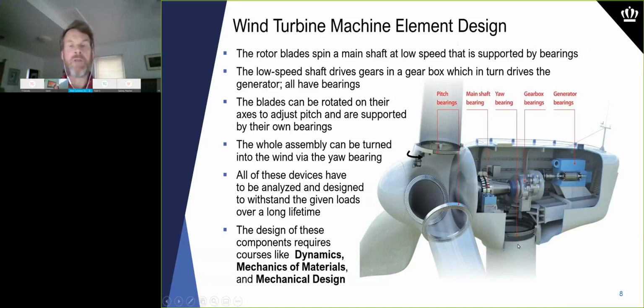We're going to rotate that on a bearing that sits on top of the streamlined pole. So we're going to point the turbine into the wind direction. And the problem is that the wind is actually varying, right? The direction's not exactly fixed. So we're going to use some sophisticated algorithms to look at the wind data, to average it over a period of time and say, okay, the mean wind is coming from this direction, and then we'll turn the wind turbine into the wind.